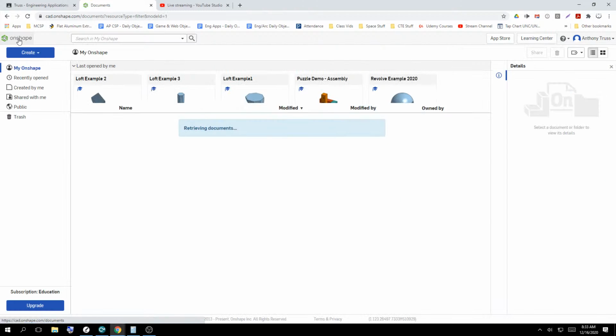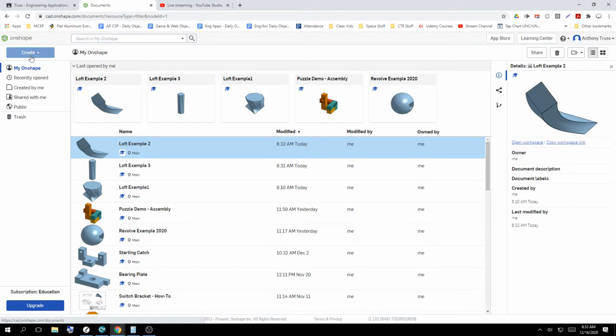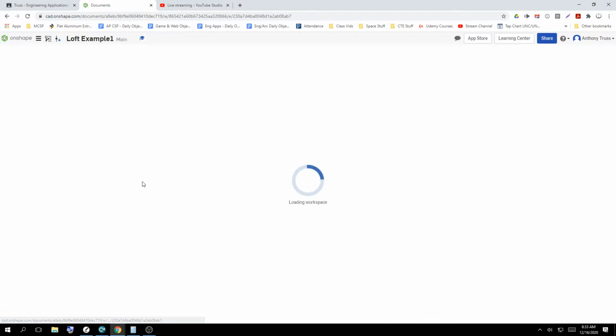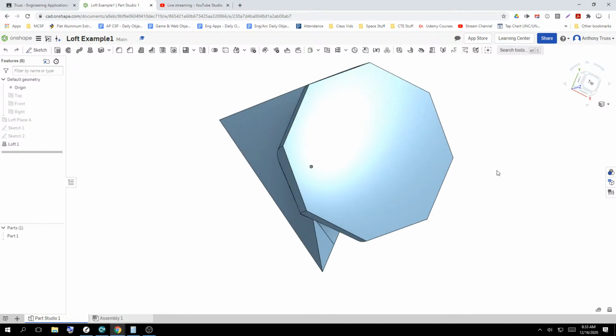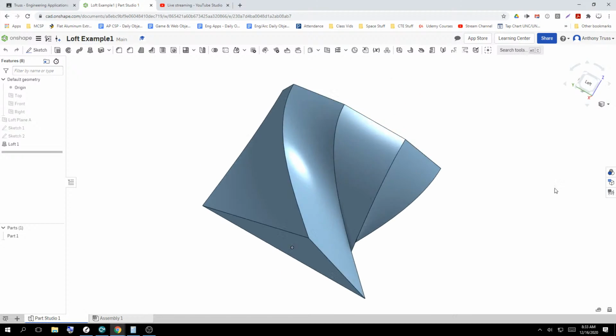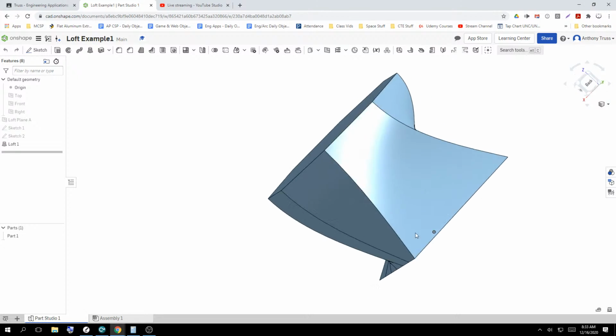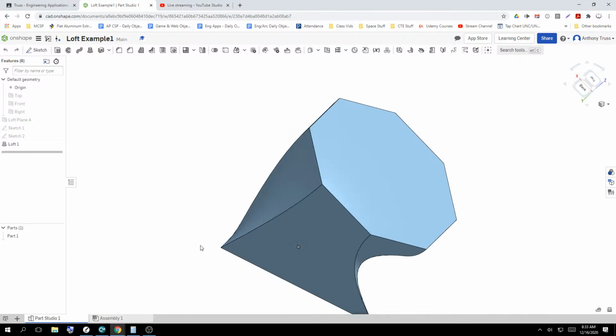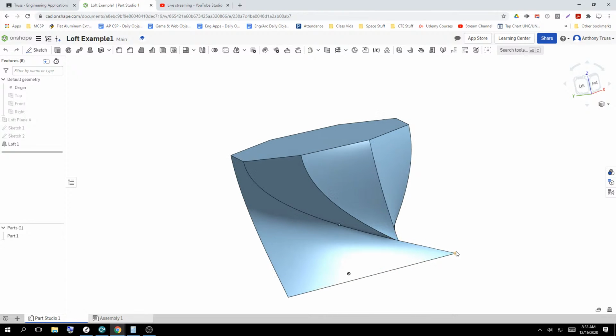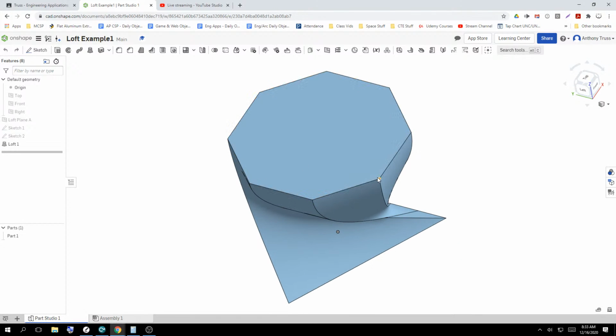Due to the fact that I want to keep this video pretty short, I'm going to skip explaining loft example 1, but one thing you can see here is I have an octagon and a triangle being lofted. When the sides don't necessarily match, you do get some bizarreness, and you could say match vertex, like this corner touches this corner, and it would probably modify this shape.